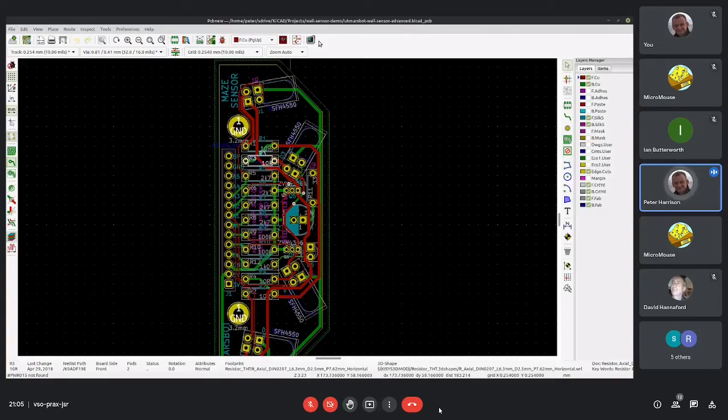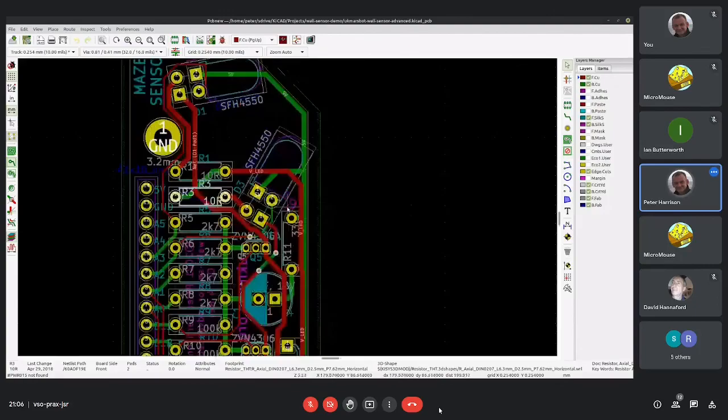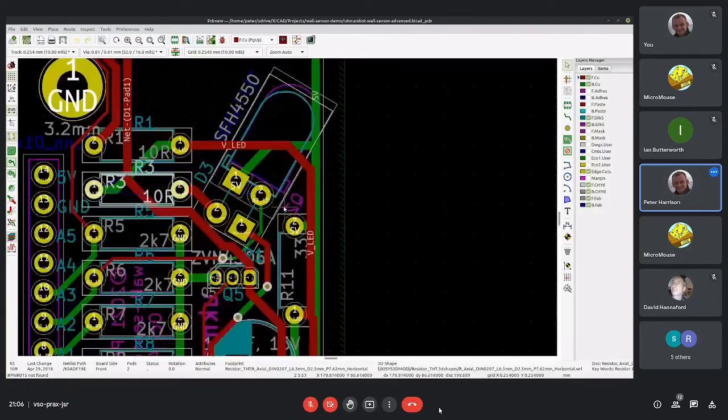And what you see on your screen at the moment is pretty chaotic. But just like in Eagle, on the right here you can turn layers on and off. Something which occurs throughout the program: there's a little arrow by my mouse pointer up here. This is the active layer, and that layer goes on top. At the moment, the active layer is the front copper, and you may just be able to see, let's zoom in, that the front copper is on top. If I change the active layer, the bottom copper goes on top, right? I find that very useful.